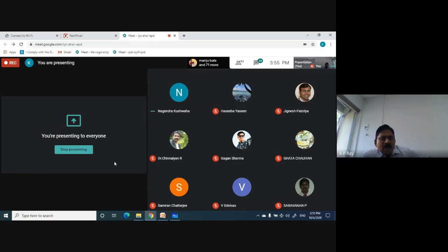You have various handbooks, and lots of papers people have written on these four types of antennas, which are generally known as IoT antenna elements. And then it is much simpler. You should know the basic physics or electromagnetics behind the design. Most of these antennas have an omnidirectional radiation pattern, which means in one particular azimuthal plane it will be omnidirectional. So designing these antennas is not very difficult.